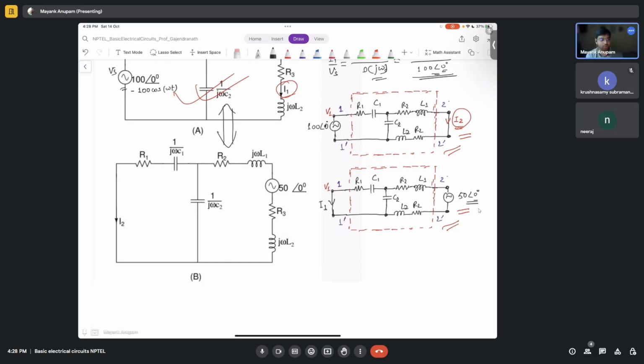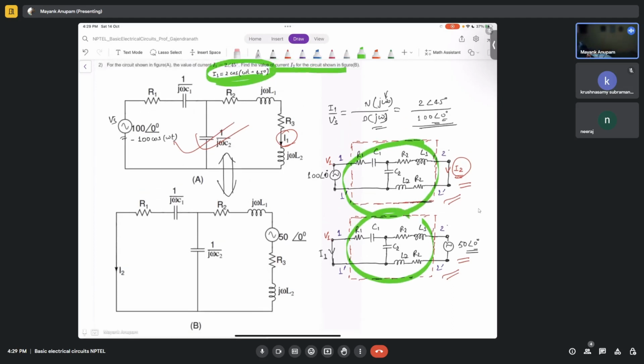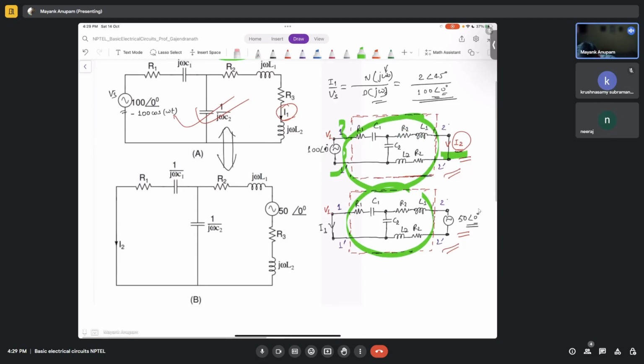Yes, very good. So this is what we need to use, reciprocity theorem here, because the circuit inside this red dotted box is linear. In the first case, we have applied a voltage source at this port here and observed a short circuit current at port 2, right? Now in the second case, I simply reversed it. I have now applied a voltage source at the second port, and I'm trying to observe the short circuit current at the first port, isn't it?